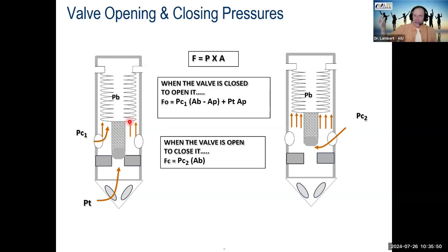It's just like air. No, it's not air. So we cannot use air in the gas lift system. That's actually a very good question. You cannot use air in the gas lift system, primarily because there are different things. Number one, if you use normal air, it has a high oxygen content. And in the presence of a spark downhole, it can actually catch fire.